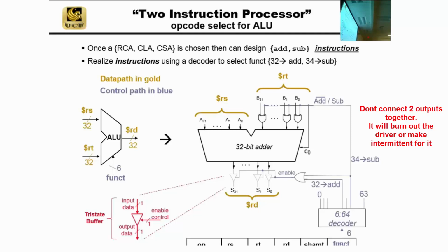So how does it decide? Actually, it doesn't decide. It's random. So that means it's a very bad thing. Sometimes your circuit may work, and sometimes it won't work. We don't like those kinds of transient faults. Race conditions are very hard to test and get rid of.